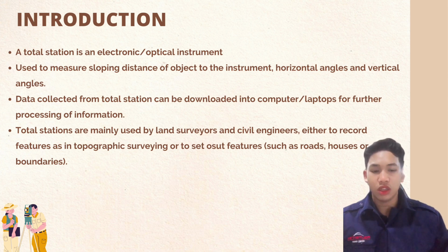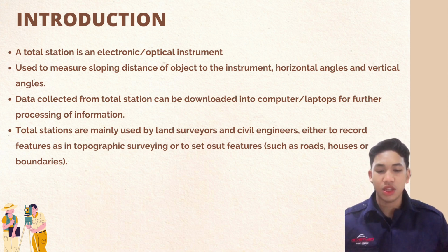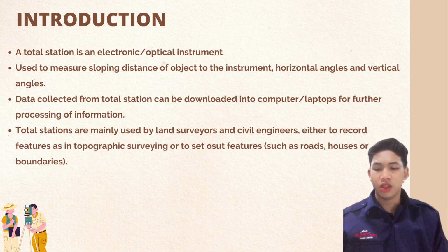This microprocessor unit enables computation of the data collected to further calculate the horizontal distance, coordinates of a point and reduced level of points. Data collected from the total station can be downloaded into a computer or laptop for further processing of information.